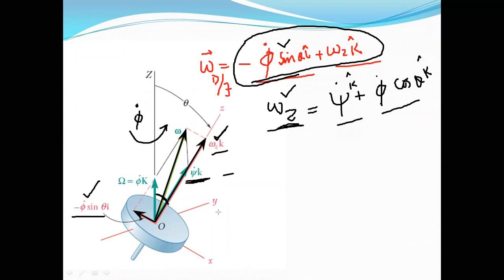This equation states that whatever be the motion in a steady precession, the gyroscope's theta is constant, the gyroscope's spin is constant, the gyroscope's precession is constant. But for an observer on the ground, the total angular velocity will be along this vector, subtending some angle, let me call this angle alpha with respect to the z-axis, and certainly we can even find the value of this angle alpha.